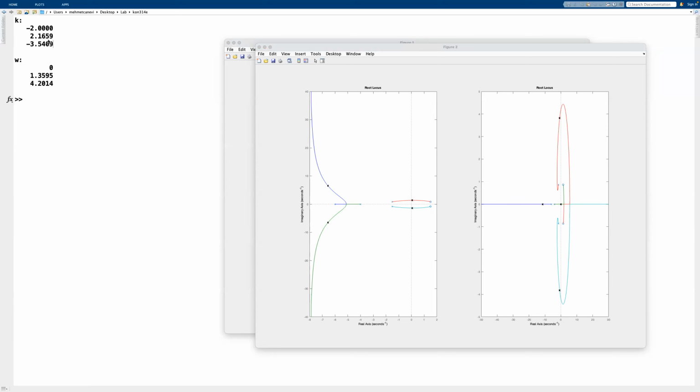I can see that from 2.16 up to infinity, the original system should be unstable. Between -infinity and -2, the system should be unstable. So we are capturing that part. That's no problem. The origin crossing here is quite accurate, but the crossing on the j omega axis is not. So the positive crossing is not accurate. So this is still an overbound.